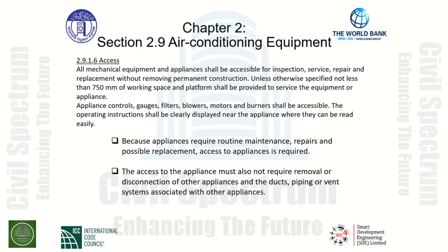The intent of this section of the code is that we cannot provide any permanent appliances or equipment in the area of the appliance requiring service. We need a clear space, approachable, and large enough for the service personnel to work on and maintain, repair, or replace the permanent appliance.